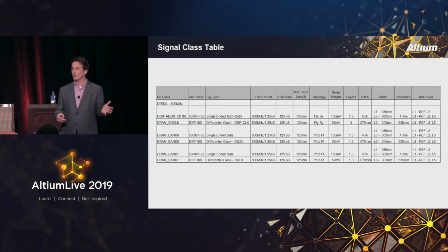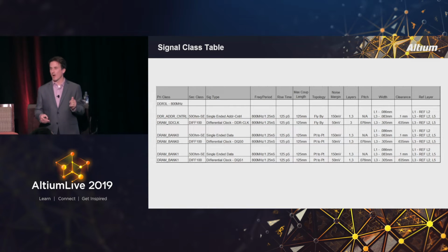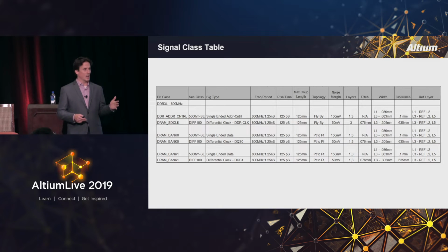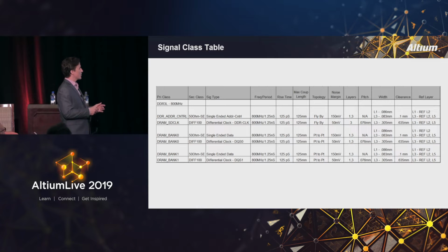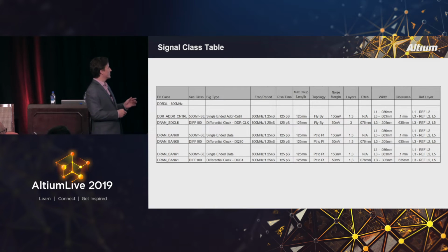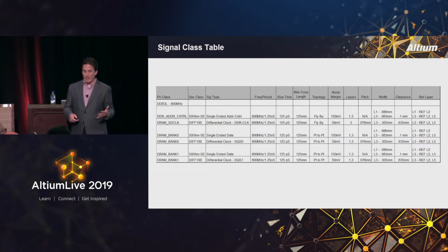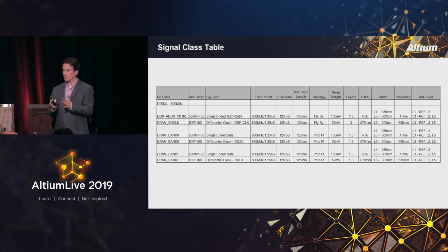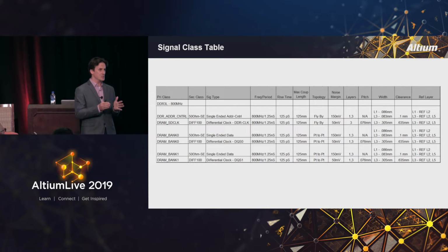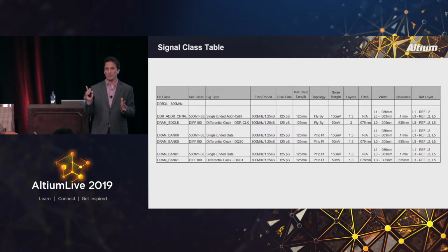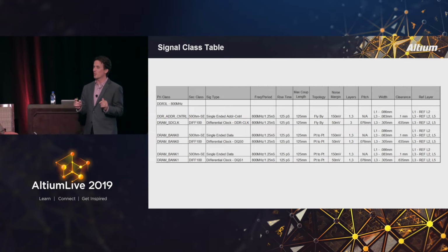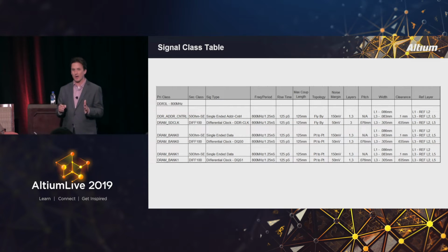I'm using a tool to look at the amount of crosstalk I have. And I set my crosstalk thresholds for specific buses, or my noise margin. I look at my topology. But what I'm doing in this pre-layout simulation is saying that if I locate two traces this close to each other, and what's the other critical parameter in this? How close they are and what?